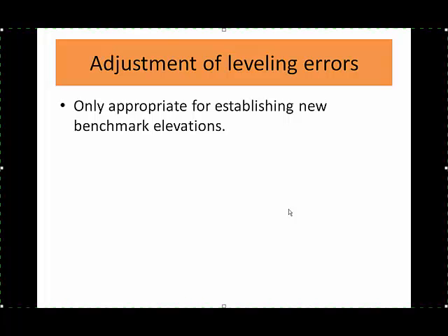Those errors have accumulated through that circuit, and they become evident when you get to the end. Well, did the errors only happen at the end? No, hopefully they were somewhat evenly distributed, but even then that distribution is a bit random. So we need to adjust an error. For every error like this, we can apply a correction.